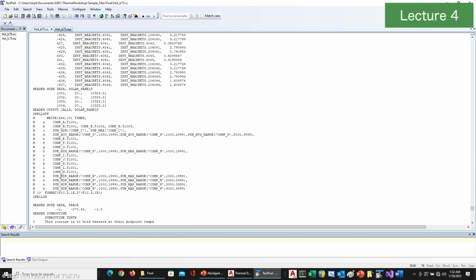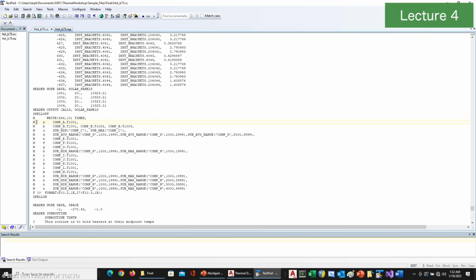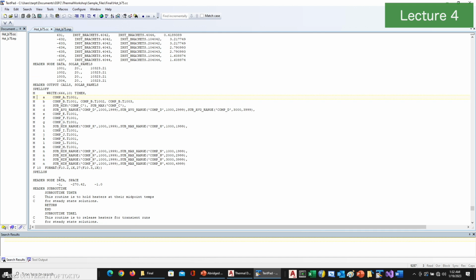So this is the file that gets written. I open up this file specifier in operations, or somewhere I open it. I forget exactly where. It writes to that file using this format. So this is basically mostly raw Fortran with the M-type statements being allowed to convert this T1001 to wherever that location for the temperature of that node is stored. And here you can see in column C, or column B. In column 6, I have the continuation lines.